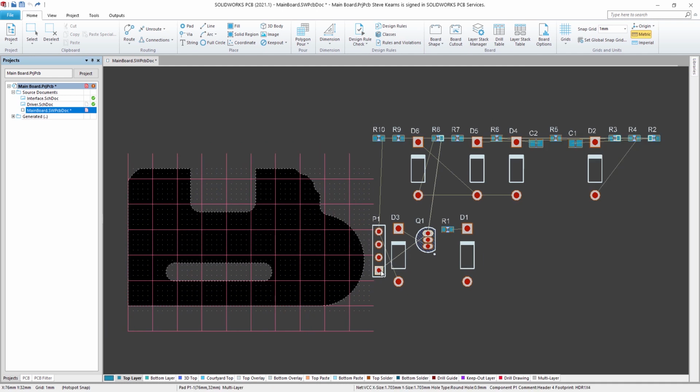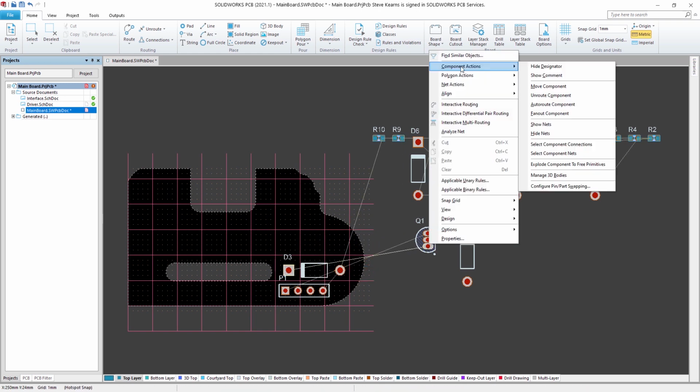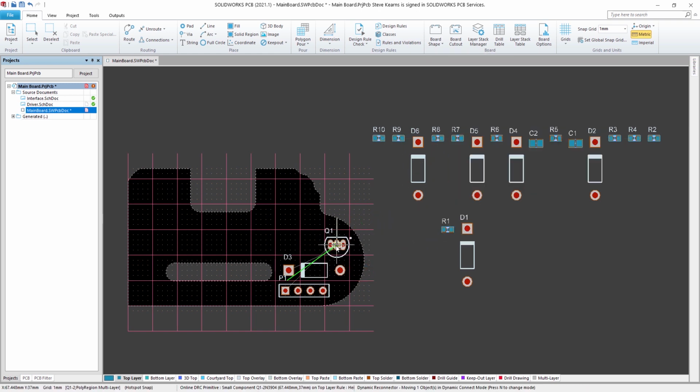Components can be placed by simple drag and drop and rotated by the spacebar. The commands like the move command, for instance, can be accessed in a number of ways. Note that the rotation is by 90 degrees. However, any angle can be used by setting in system parameters, here set to 30 degrees.